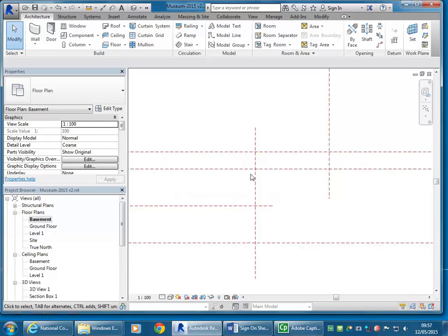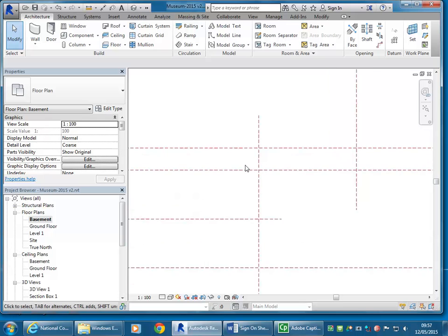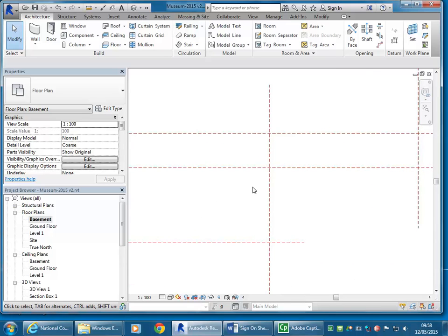And again, you can work all of this out in plan. At that corner there, remember you're going to have a step, and then it goes to the landing, and then another step here. So really at that corner point, you're going up 2 rises in no distance. And so that is going to cause a problem with the stairs, but an even greater problem with the railing, because the railing has to go up 2 treads in next to no distance.